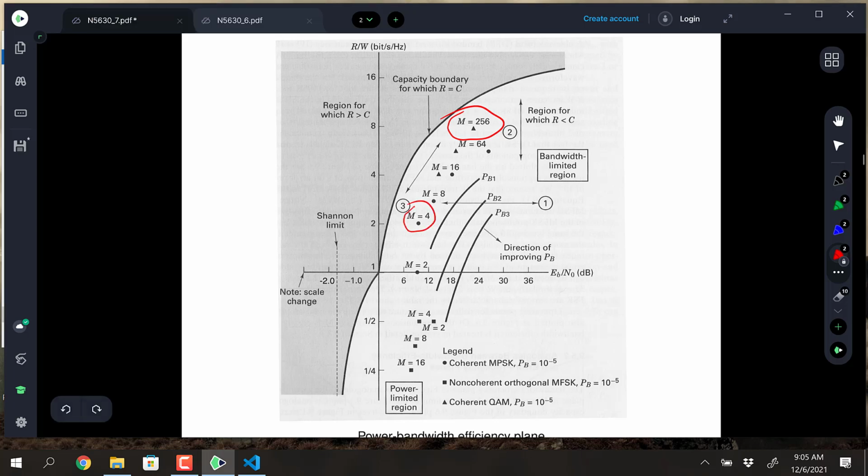Here we can see our QPSK and BPSK. And then for the really high order MFSK, like this one, they're all in there. They're not super fantastic. If I look at the distance, and how you measure distance, of course, is subject to your interpretation. In this case, the error probability is 10 to the minus fifth for all of those points. So that's small, but to talk about arbitrarily small means you actually have to pull further away from the curve to operate at a higher Eb over N naught.